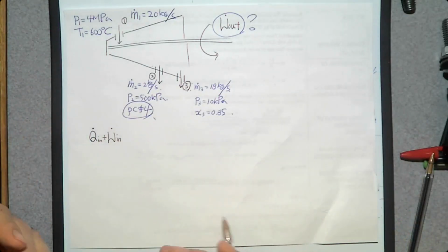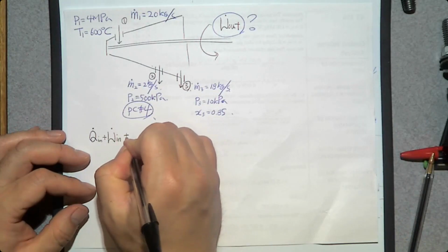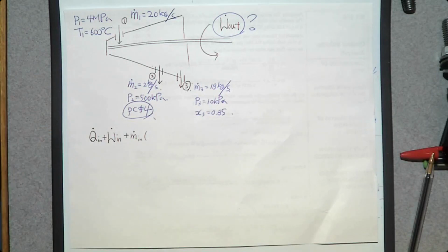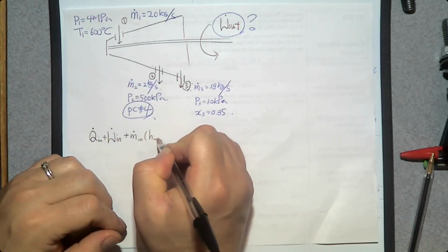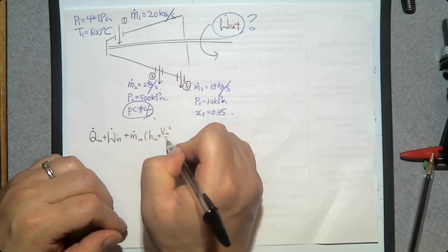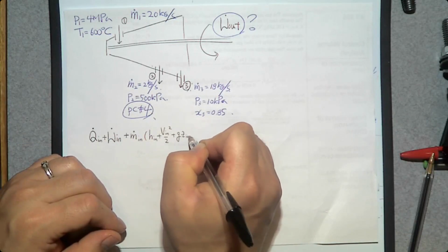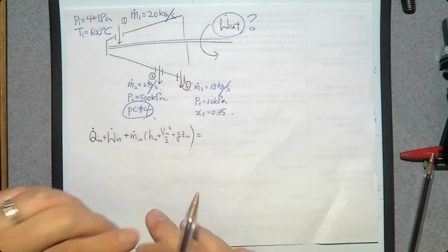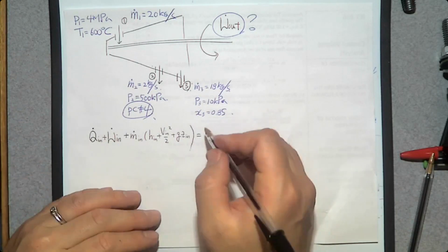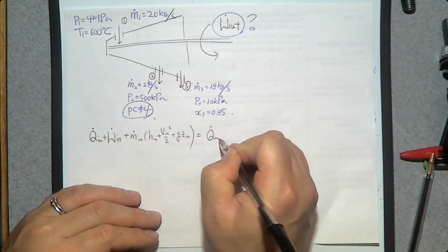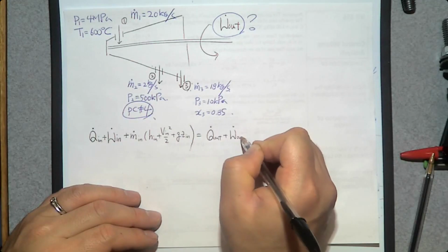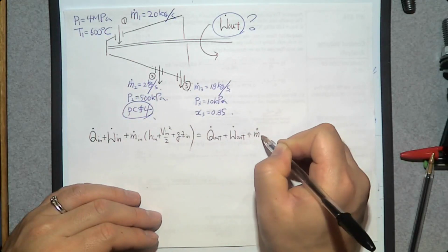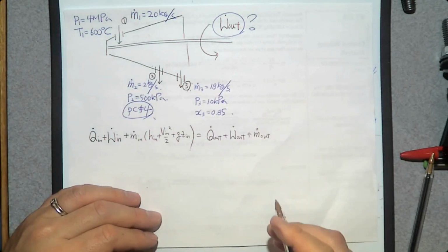Now we have a mass flow rate at the inlet, m dot at the inlet. And this mass flow rate has what? 3 forms of energy: enthalpy, kinetic energy, and potential energy. And those 3 are energy transfers into the system. Now there are energy transfers out of the system. First, heat. Second, work. And last, energy by mass, m dot that goes out of the system.